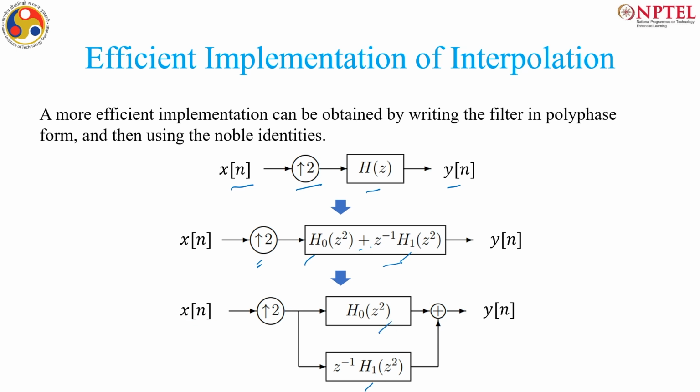Because this is being decimated in time. So, this is half of the components which are the even samples and these are the odd samples, and these two get convolved in parallel. So, this is doing a parallel computation, so it will be faster, that is fine. Now, what is the problem? This is operating at twice the sampling rate. Of course, the same thing is happening here, but how to solve this issue?